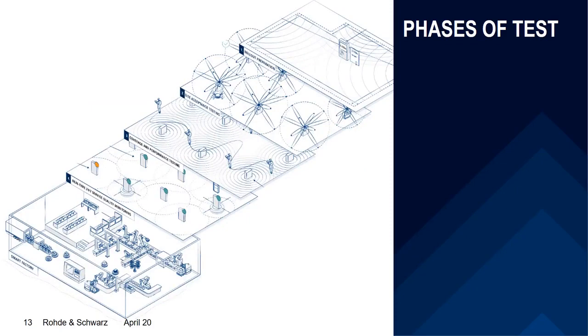Now, if you start deploying such a network, what are the testing requirements, or what should you actually do to make that a successful project at your end? Well, first of all, you should look into your area and make sure that the spectrum you would like to operate is not interfered with by any other electronic devices. I said earlier that in Germany we have this specific situation that we are allowed to use a spectrum portion between 3.7 and 3.8 gigahertz dedicated for 5G or LTE operation, but only allowed for your own premises or your own ground. So you can apply for that spectrum and then it's yours. Obviously you want to make sure that there is no interference in that spectrum before you do your rollout. That is the preparation phase.